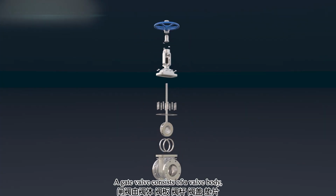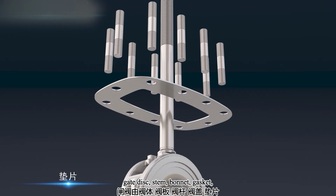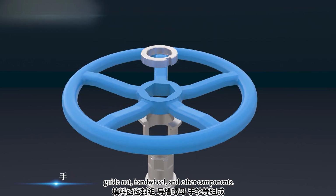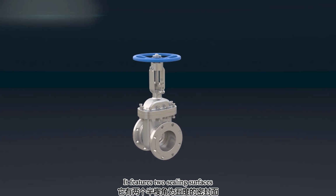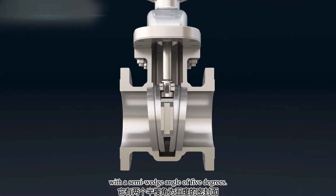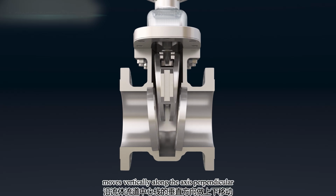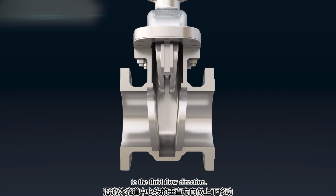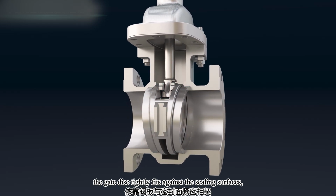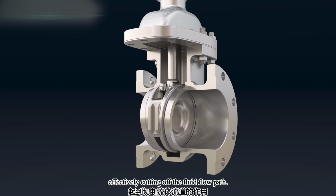A gate valve consists of a valve body, gate disc, stem, bonnet, gasket, stuffing box, sealing assembly, guide nut, hand wheel, and other components. It features two sealing surfaces with a semi-wedge angle of 5 degrees. The wedge-shaped gate disc moves vertically along the axis perpendicular to the fluid flow direction. When the valve is closed, the gate disc tightly fits against the sealing surfaces, effectively cutting off the fluid flow